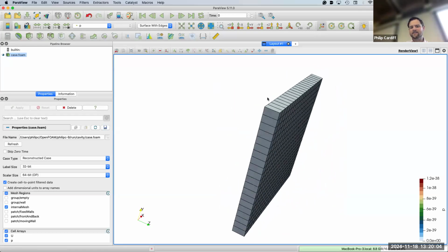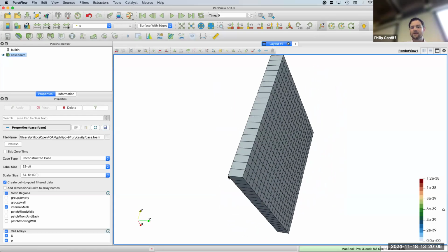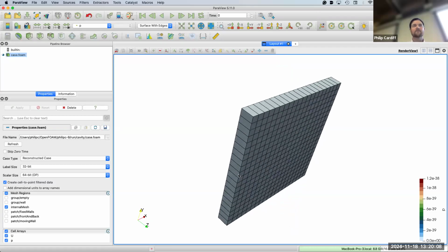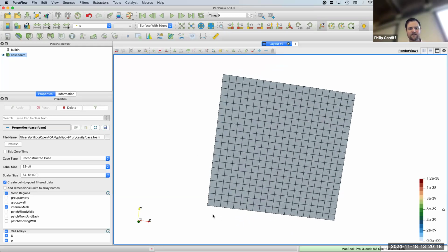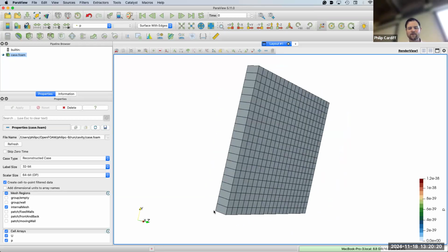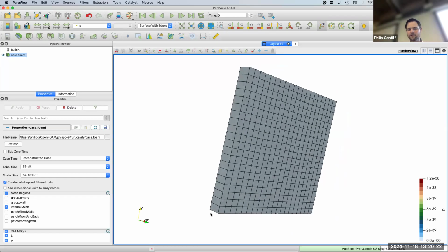So to define this geometry, we just have to give the 8 coordinates of this block. If we had some other geometry that needed multiple blocks, we would just give the corners of those blocks. In this case, we'll have a coordinate down here in the bottom corner, which is the origin, and then we'll define the points in one plane and then the points in the second plane.